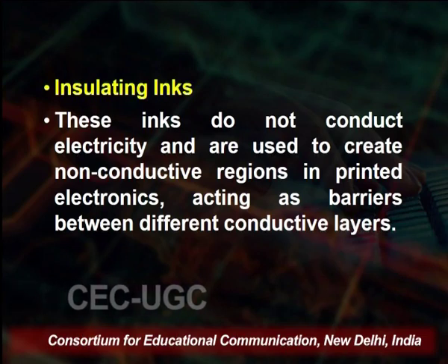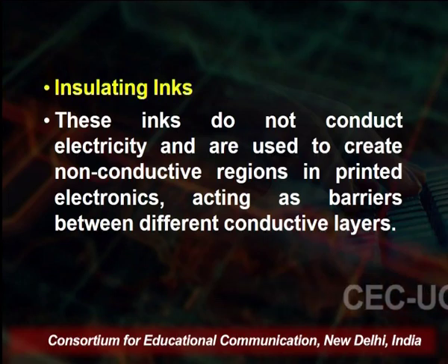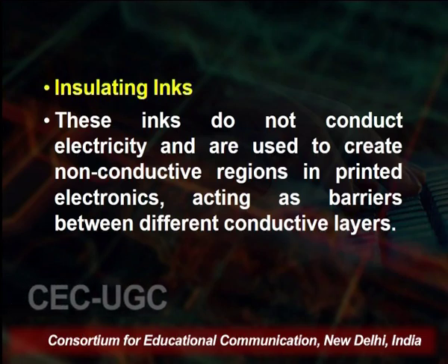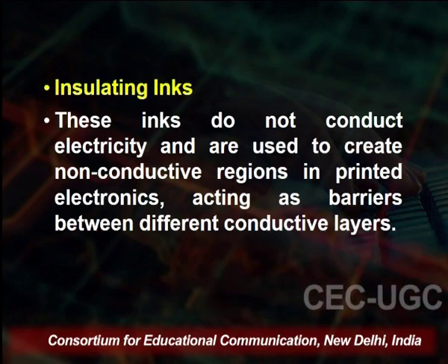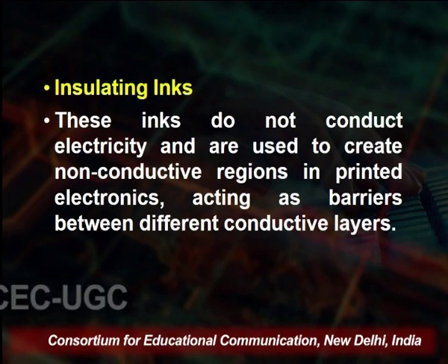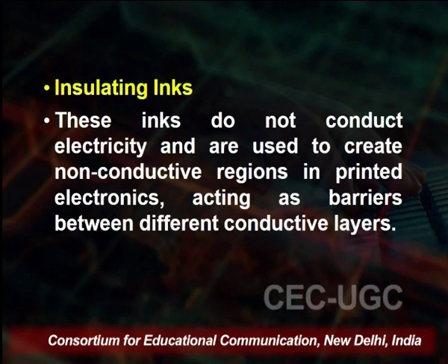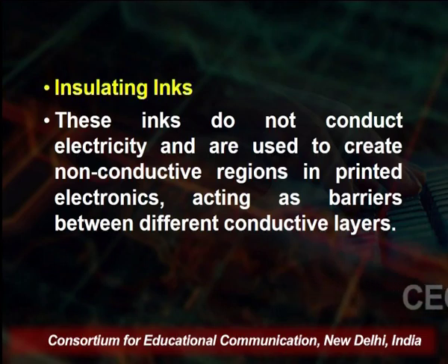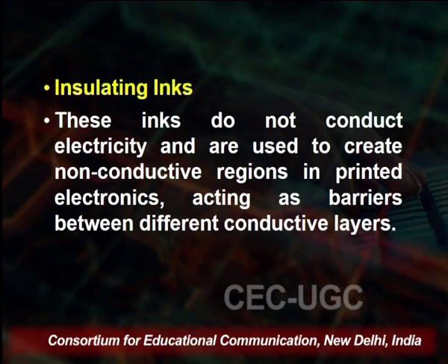Another type of ink is the insulating ink. These inks do not conduct electricity and are used to create the non-conductive region in the printing. So in printing electronic devices, insulating inks are used whenever we create a non-conductive region in the printed electronics, acting as a barrier between the different conductive layers.